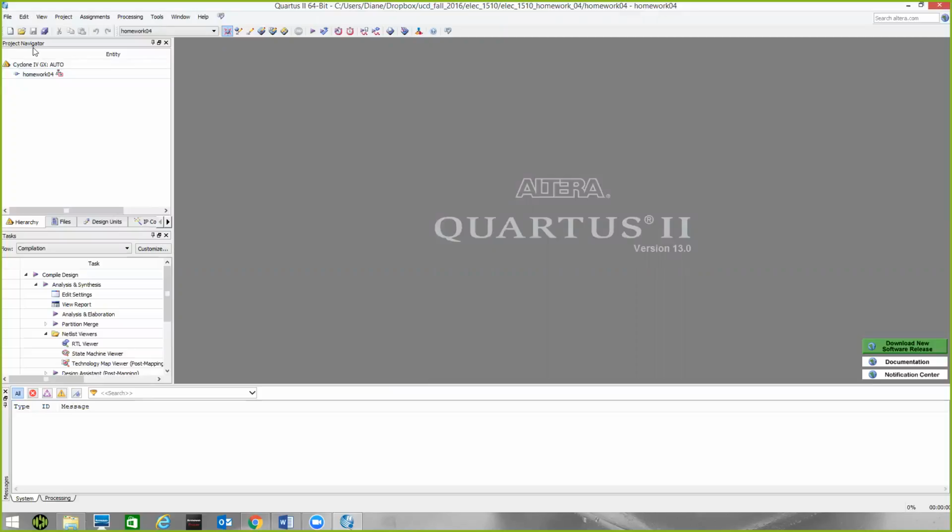All right, so here in the Project Navigator window under Hierarchy, we can see this is the chip that it just selected for us, the default. We won't worry about that, like I said, until we program the board. This is the name of our top-level design. We'll learn more about that later. I'm going to click on the Files tab, and notice we don't have any files in our project.